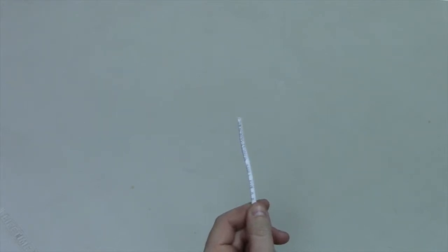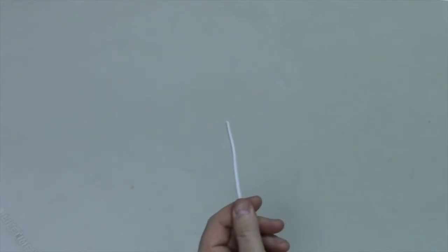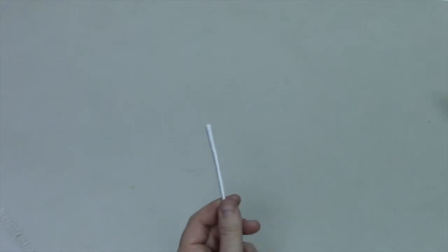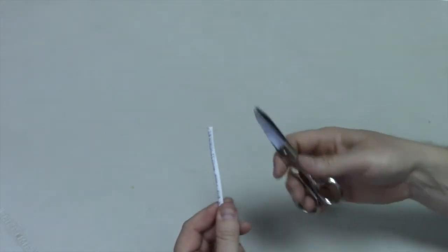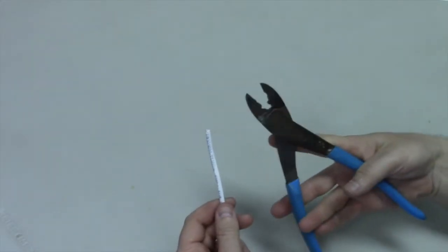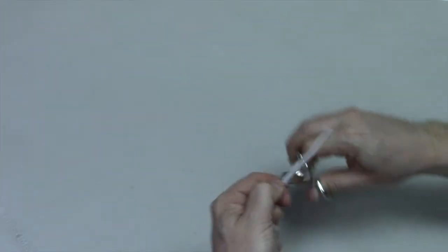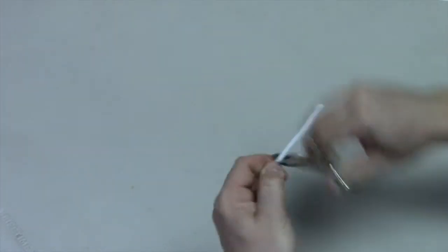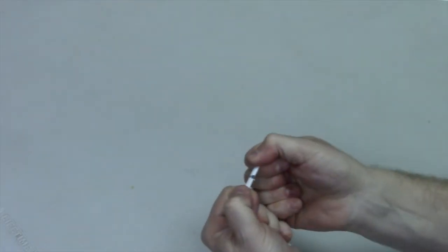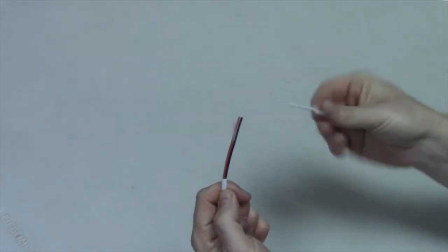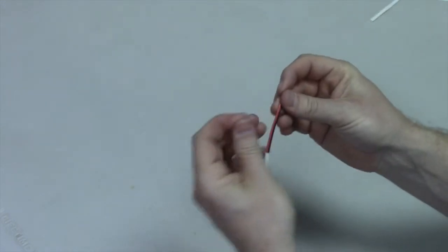We'll start with the speaker wire. For the purposes of this video, we are using 16-2 speaker wire. Remember, that means it's 16 gauge with 2 conductors. To strip off the sheathing, you can use scissors as we did in the other videos. You can use your wire cutters if you're comfortable with that, or you can use wire strippers. For this video, we'll use scissors again to score the sheathing. Pull off the sheathing. If you need to reveal more wire, you can use the string as we mentioned before.